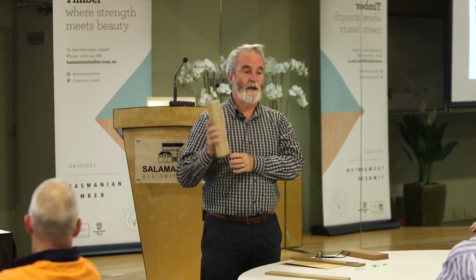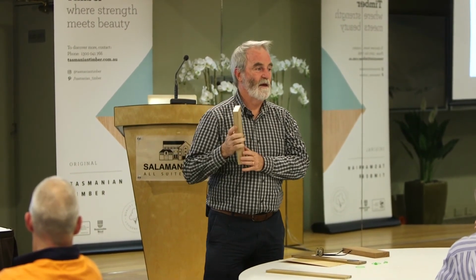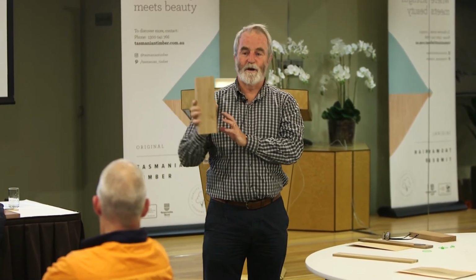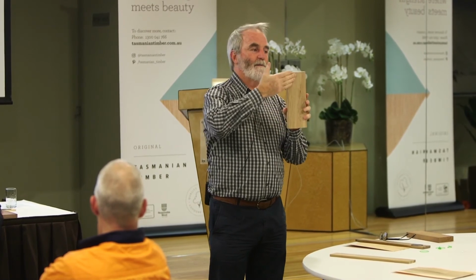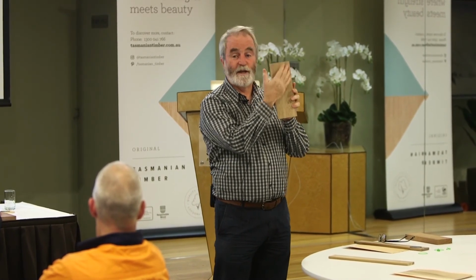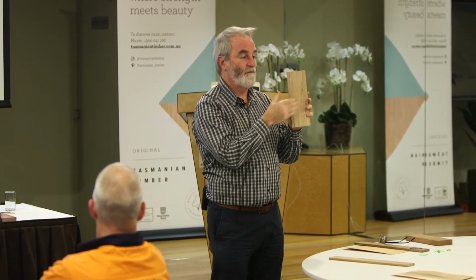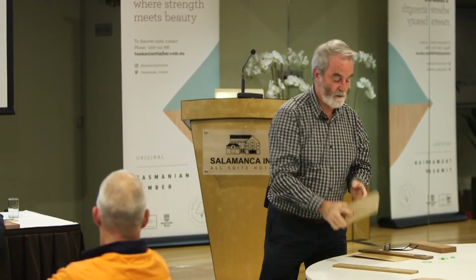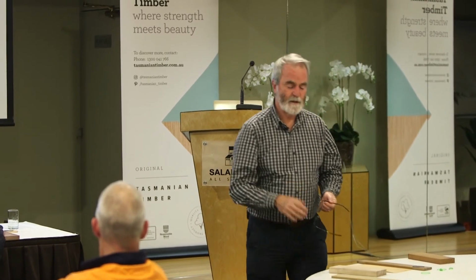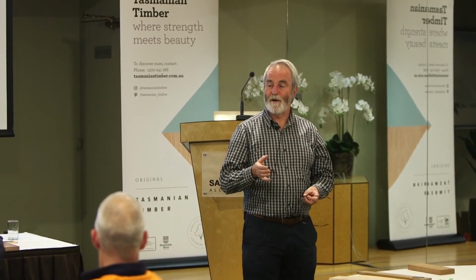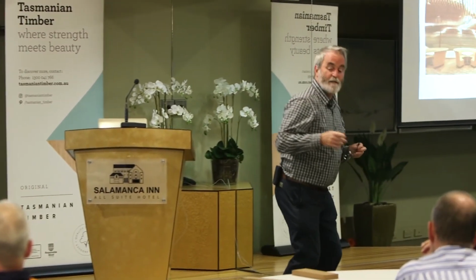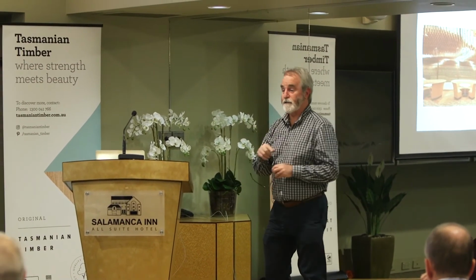So if you've got clear coatings, you're used to recoating things. If I put it in a window frame where it's sunny all the time, and I'm using a polyurethane finish, I'll find that start to come off after 7 or 8 years. It'll come away powdery. There's not really much you can do about it unless you can keep it out of the sun. Certain species then will also change colour. We mentioned celery-top before.